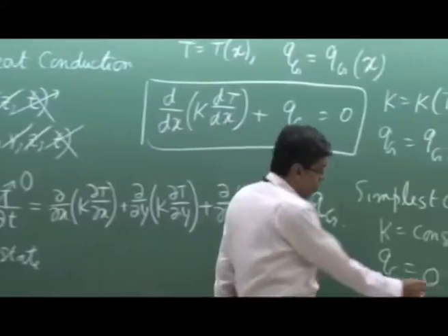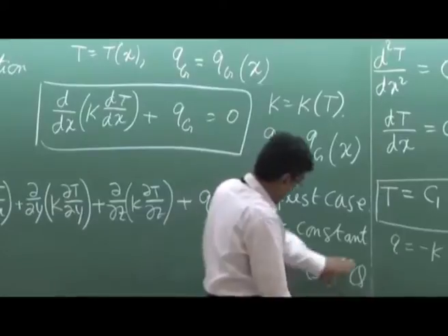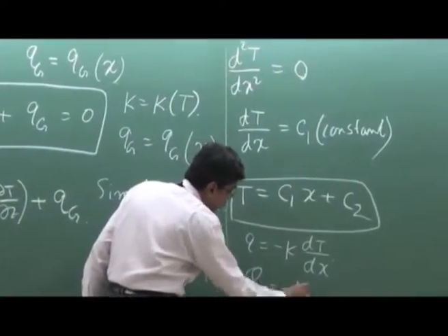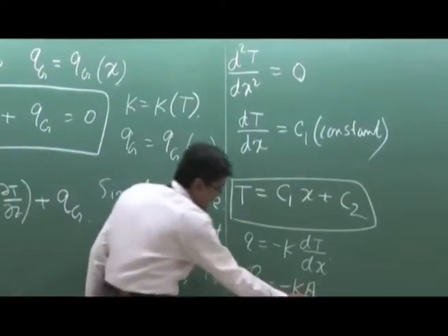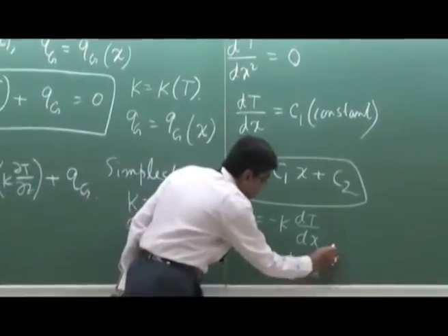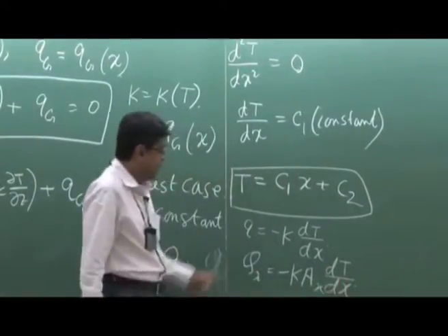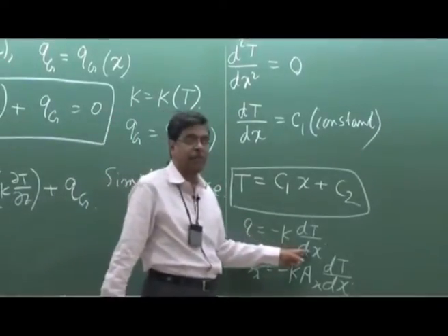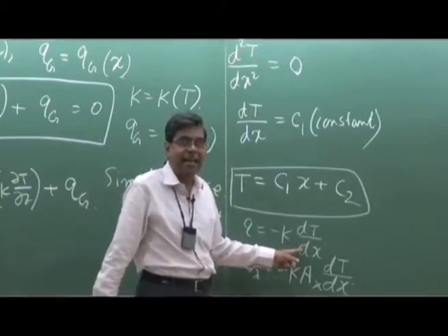And if we find out the heat flux over an area, then we multiply with the area A. I write A_x, meaning the area normal to the x coordinate, but this x is not required because the heat flux is defined per unit area normal to the direction of heat flow, and heat flux is proportional to the temperature gradient along this direction.